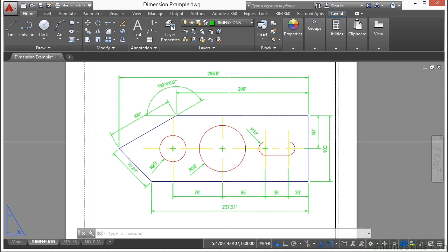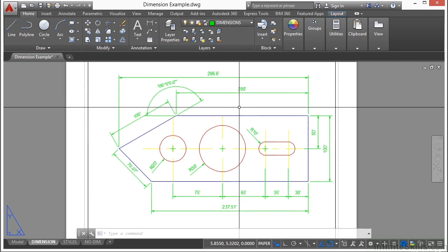I recommend that you always use associated dimensions, especially if you're placing your dimensions in paper space, as is the example here. Dimension associativity defines the relationship between your objects and their dimensions. Now, there are three types of associativity between geometric objects and dimensions. Associative dimensions automatically adjust their locations, orientations and measurement values when the geometric object associated with them is modified. And dimensions in a layout may be associated to objects in model space. That's where the DIMASSOC system variable is set to 2. We'll go over this later on.